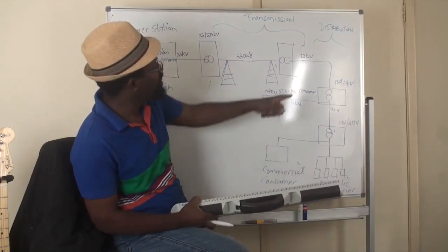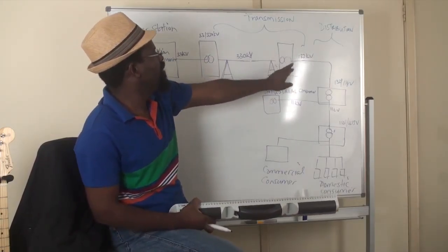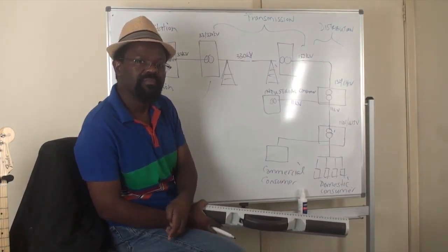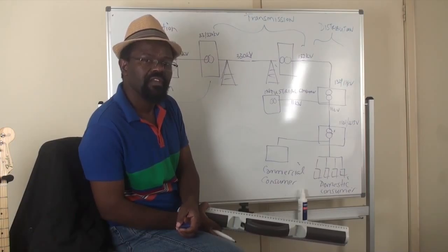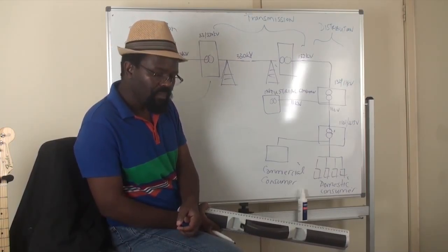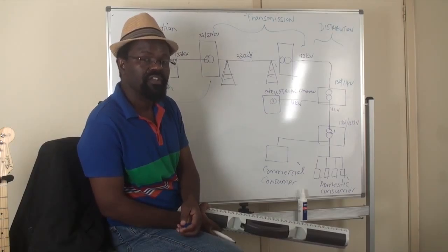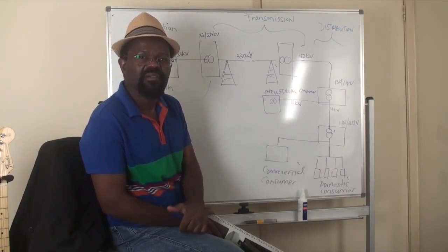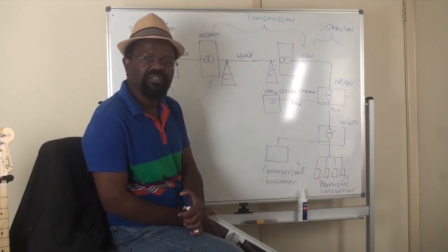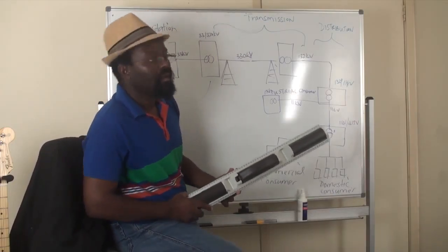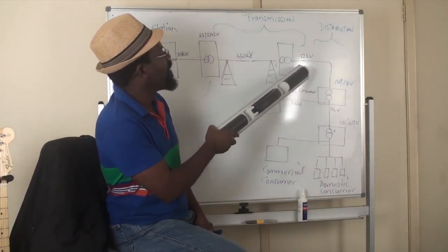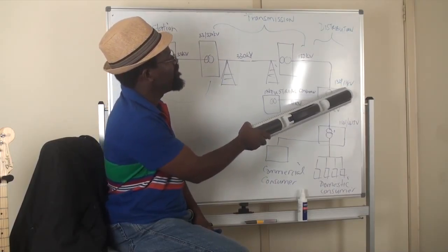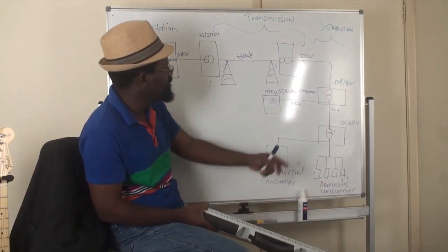Then, either on this one or on the 132 kV side, you can feed customers. There are customers who want power at the 132 kV level, and these are industrial customers, like smelters or those big customers. The other customers are fed from this substation here, which is 132 kV to 11 kV. On the 11 kV side, you can feed them there.